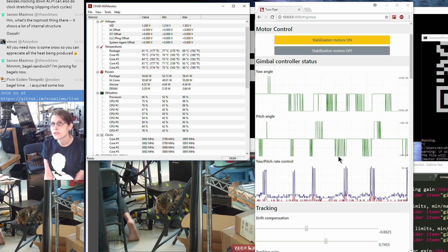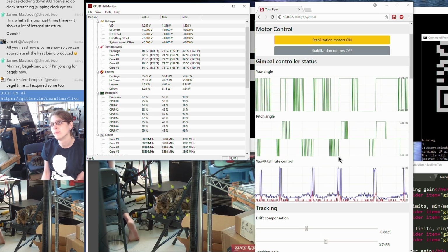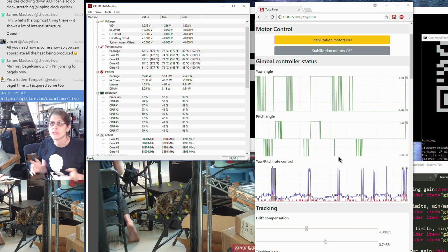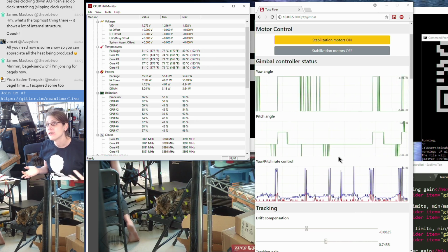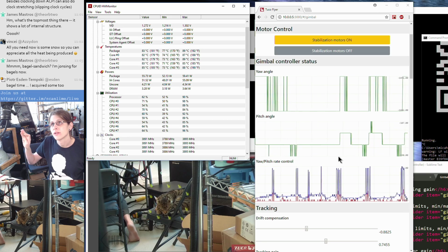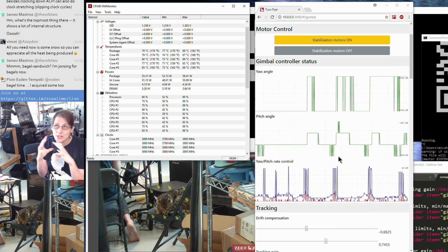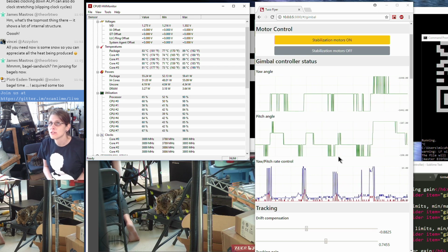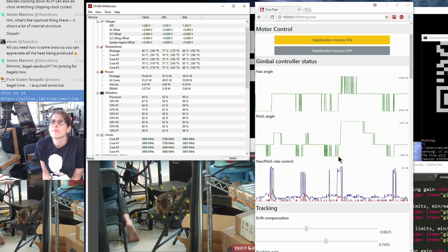And the whole architecture here is based on this shared message bus that a bunch of different clients all get to snoop in on. The main message bus client, which is also the only message bus sender, is the robot control loop, which is the center of this whole thing. But then there are peripherals stuck on all over the place, like the computer vision algorithms in this web browser.